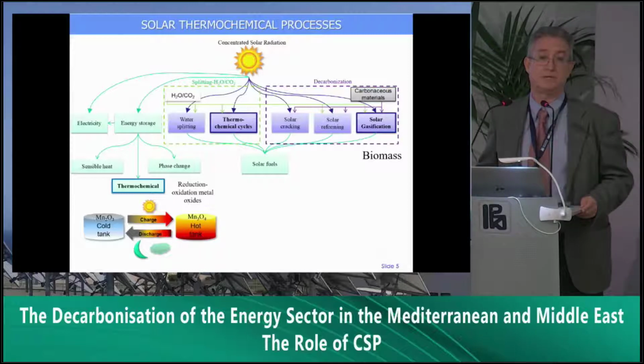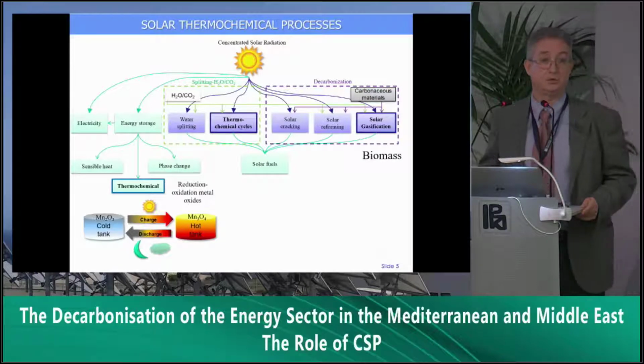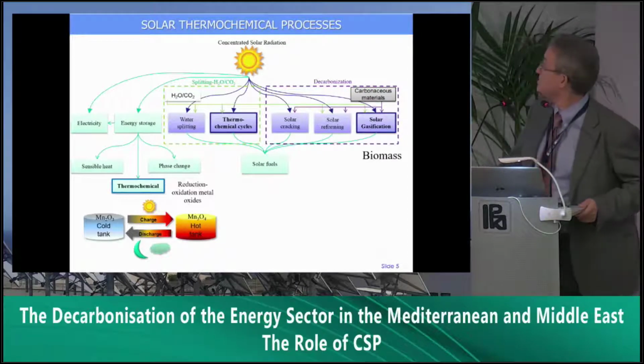For example, in a typical gasification process, sometimes we need to gasify 1 kilo of carbon or coal. We might need sometimes even 1 kilo of additional coal for this purpose. So this means that if we can replace the part of the biomass or the fuel that is used to heat up the process, we can reduce as much as 50% the CO2 emissions.